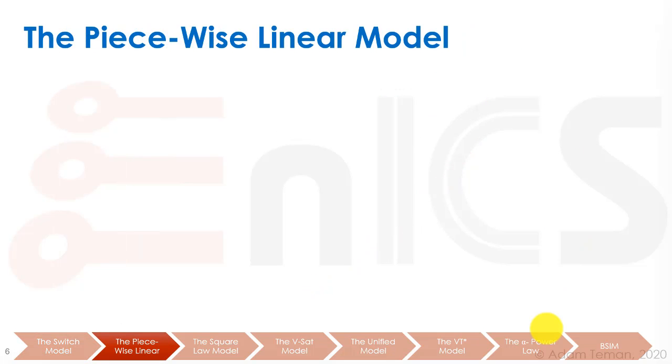So let's start making it a bit more accurate, trading off the complexity of the model, what we can do with hand calculations or even in our head, against what we can do with a computer, and maybe we can't even do with a computer because it becomes very complex, such as those TCAD models that we said are only for 1 or 2 devices. So our next step would be a piecewise linear model. Piecewise linear models are often used when we want to simplify things that are not linear, and they're not that nice, but it makes it much easier for hand analysis.